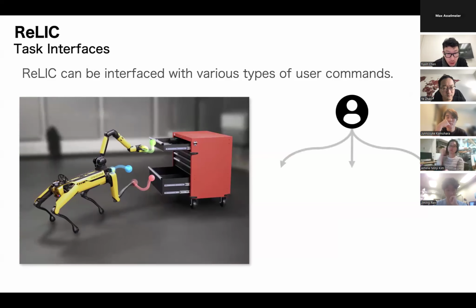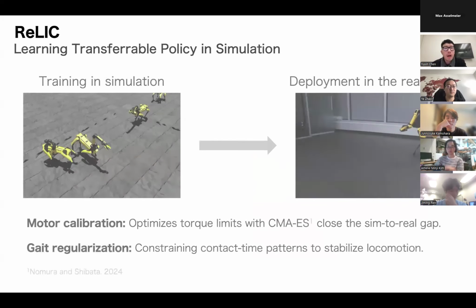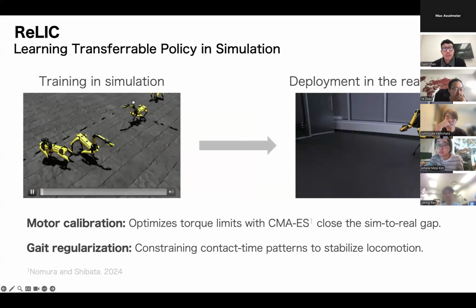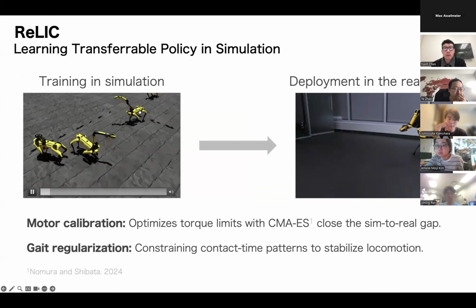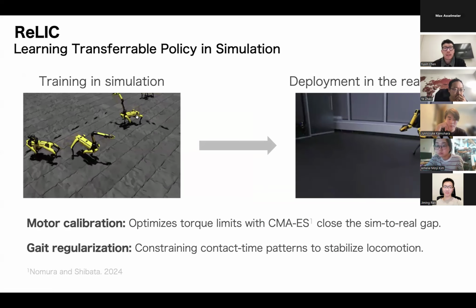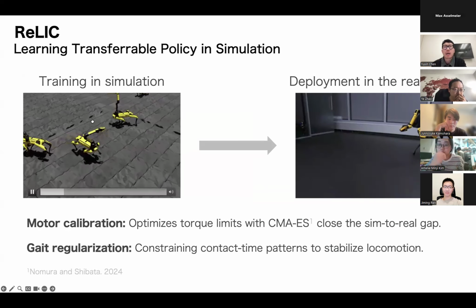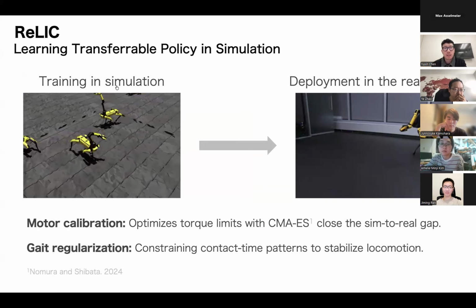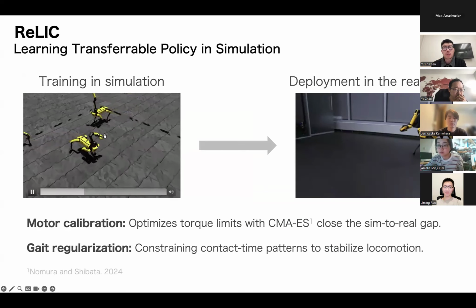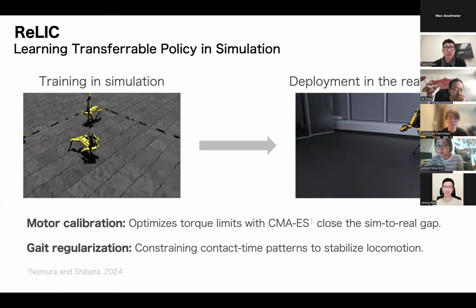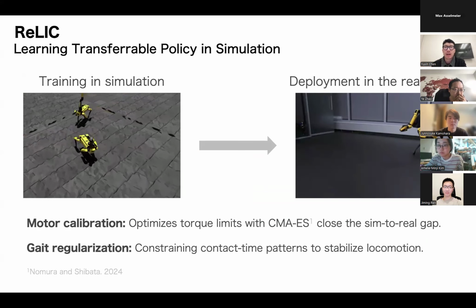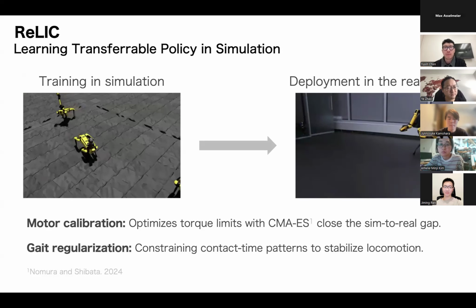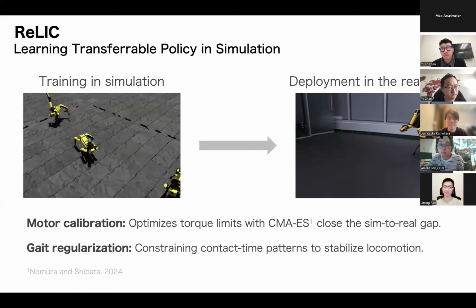Let me see. I have a figure here. So during the RL controller training, we keep this arm here, but the arm just does some random stuff, and the RL controller just tries to stabilize the robot and track a predefined body trajectory with either 3 legs or 4 legs. And the upper body, like this arm, we just give some random motion to simulate the actual deployment scenarios. For example, the external forces, the change of center of mass, like in that case.